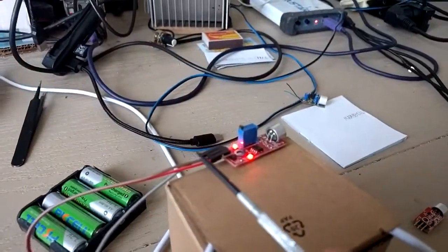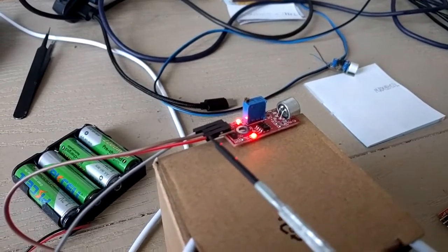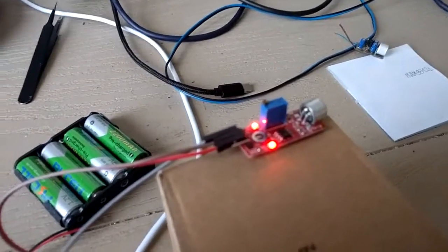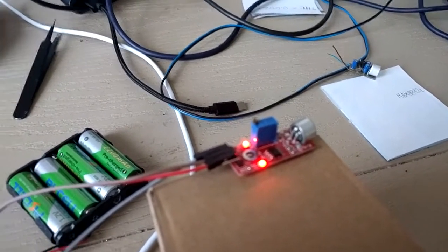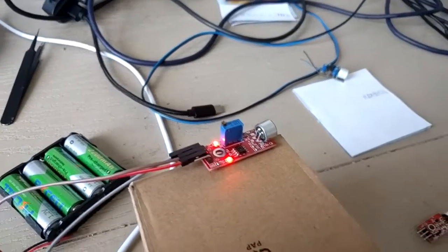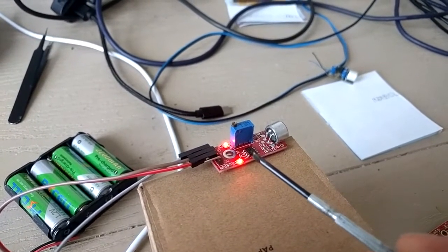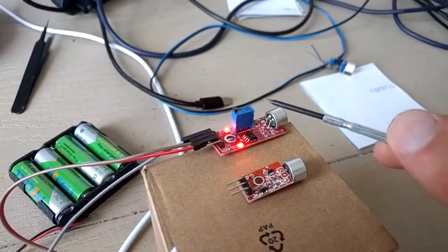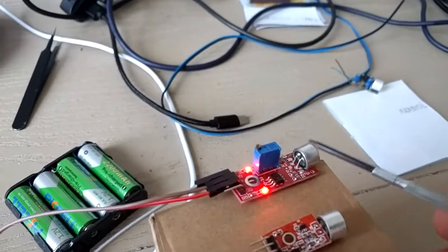So as we have seen, the voltage at the output of this device is 0.1 volts. It's way too low for the sound card. Probably going to have some noise with this signal, so it's not good for the processing device. And secondly, the distortion of this device is pretty high. It's around 2.5%. So those two devices are comparable. The distortion are comparable, just slightly higher distortion for that one.